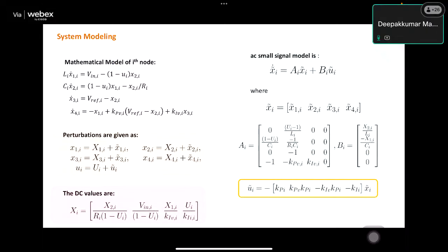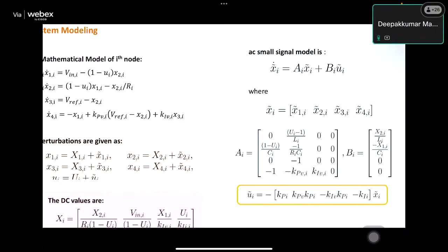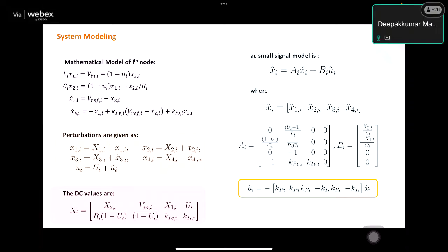See, what is the order of the boost converter model? This is second order, fine. When you model the boost converter in state space, it will turn out to be second order. But if I control the boost converter through a simple PI controller, then my total order of the system will become higher, because I will be using a dual loop PI controller. So I have two integral actions. That will result in a fourth order model if I model the controller and plant together.